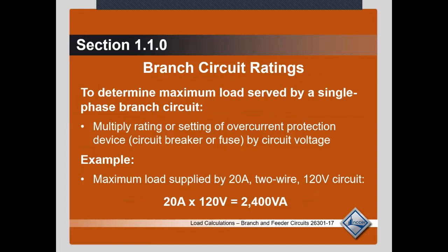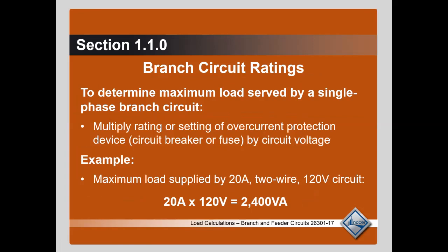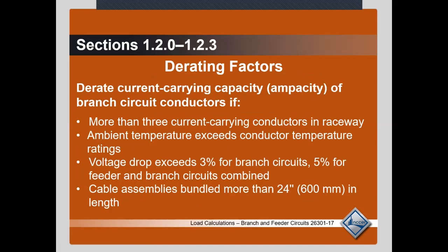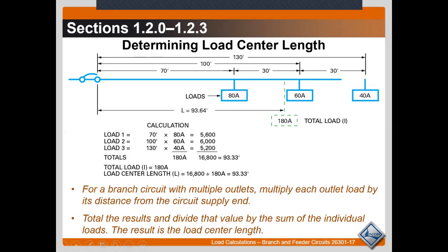So for example, if you have a 20 amp, 2 wire, 120 volt circuit, then obviously it's volts times amps equals your volt amps or watts, right? So derating, current carrying capacity of the branch circuit conductors. If you have more than 3, we talked about that, ambient temperature, and so forth.